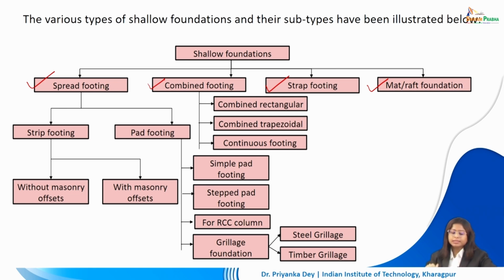Pad footing can either be a simple pad footing, or we can have a stepped pad footing. Again, here we are providing some offsets for the load transfer at a certain angle. For RCC columns, you actually have an integrated RCC pad footing.